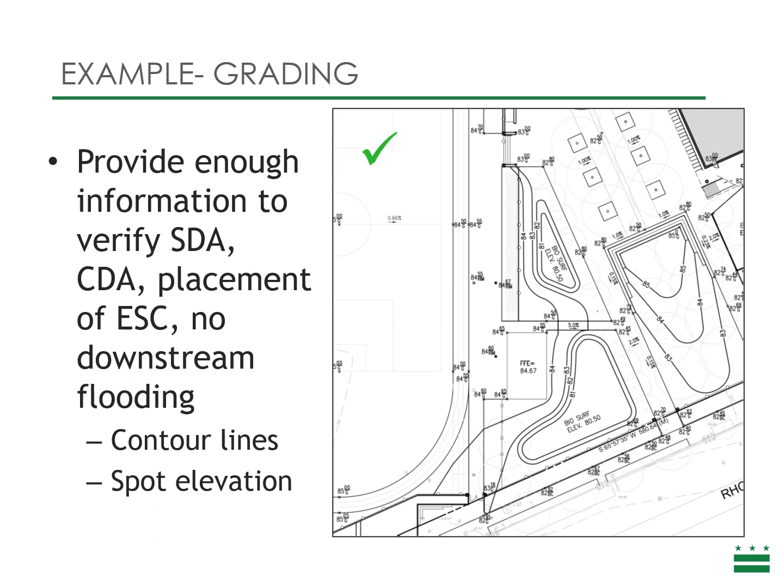The next sheet we have is grading. It's important to provide enough information to verify the site drainage area, contributing drainage area, placement of erosion sediment control, and to show that there will be no downstream flooding. You can use contour lines or spot elevations to show this.